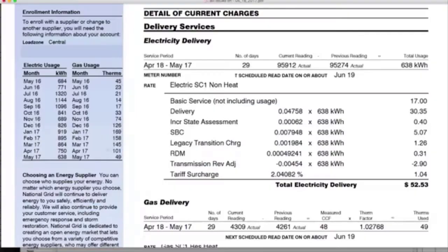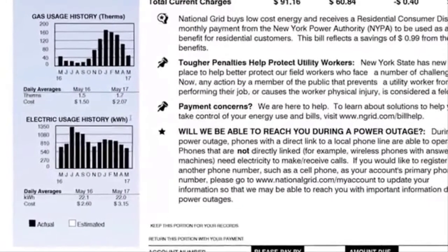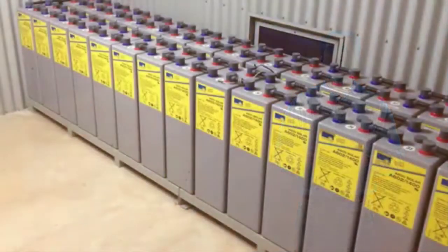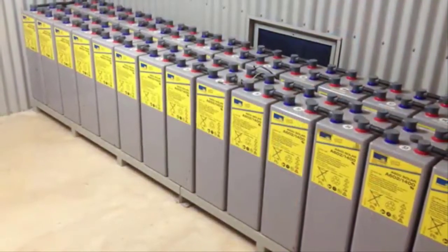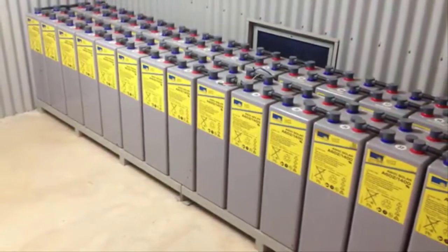A simpler way to determine energy demand when dealing with a grid-tied building is to use a utility bill. Remember that energy demand use is an annual event, but it does vary day to day and possibly month to month or seasonally. So while we could calculate daily energy use, we typically plan solar for annual demand. The only time daily variations in energy is critical is if you're working off-grid or need to make sure that a battery or a photovoltaic system can support the maximum daily energy demand.